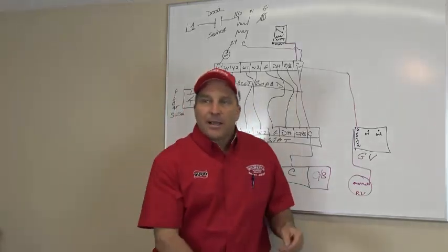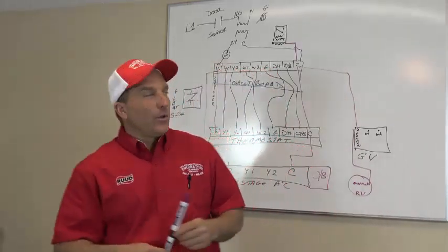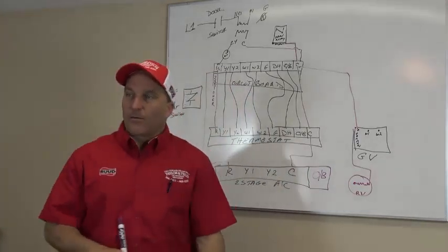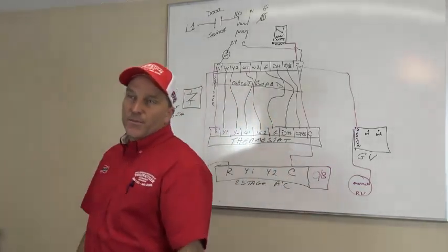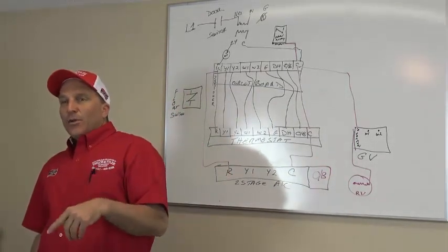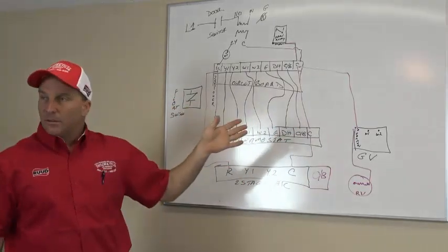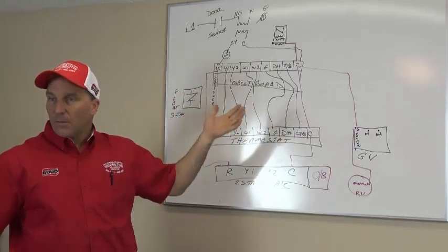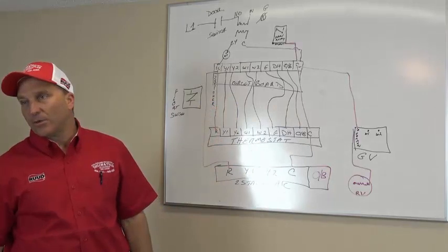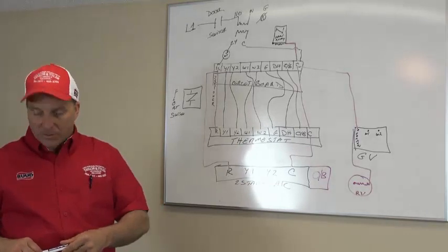Okay, let me ask you this. If you walk into a house, and I want to shut off my inside unit, and the reason I want to shut that off, well, if I shut my thermostat off, what runs? Nothing. What the communicating system was, what they actually want you to do by the book, is they want you to break common. Can you break common with a float switch? Yeah, definitely you can. They want you to break common with the float switch because you're losing the voltage. You open up a circuit somewhere, so that's the whole key to it.